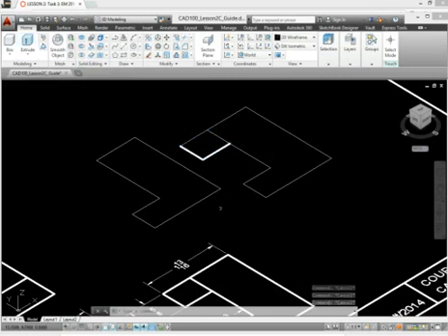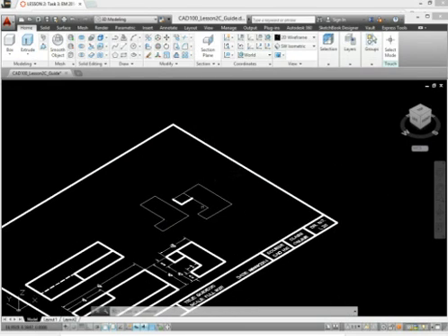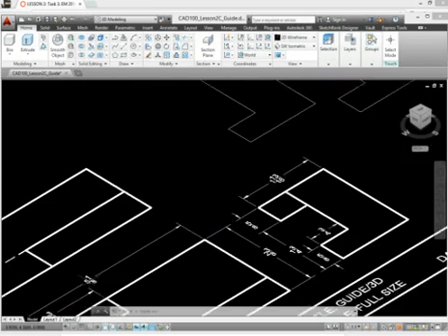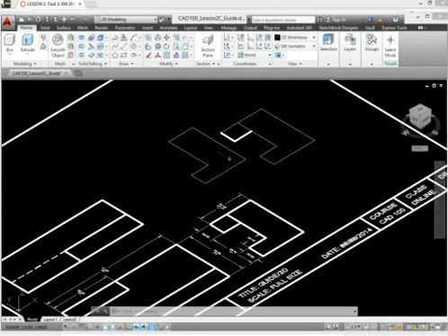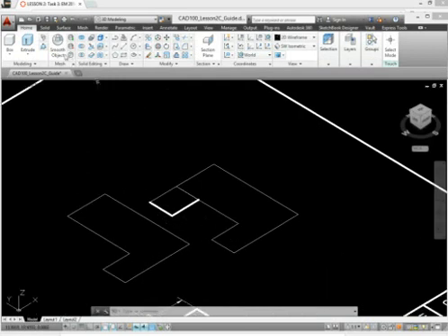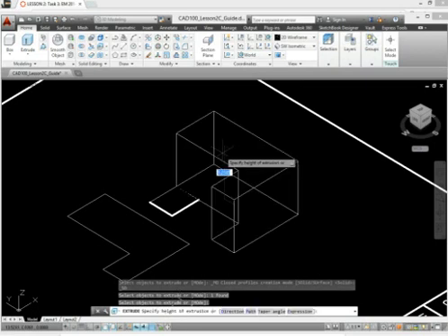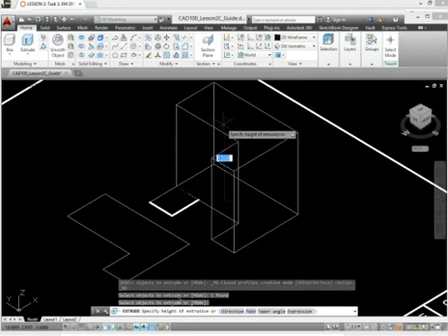We're going to have to extrude one at a time. Remember that, one at a time. The first extrusion, the largest piece, is going to extrude 5 1/8. The smaller one, 2 3/8. Okay, pick extrude, pick your region, hit enter. The command will ask you the height of extrusion as you see it happening in real time. Type in 5 1/8 and hit enter.